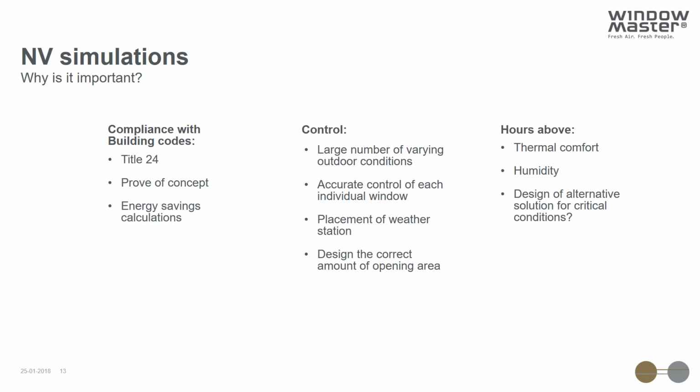Then we will also need something as simple as where do we place the weather station to collect data. And at the last, one of the challenges with natural ventilation is, of course, thermal comfort. For example, we need to know how many hours a year we will have the critical conditions with natural ventilation.